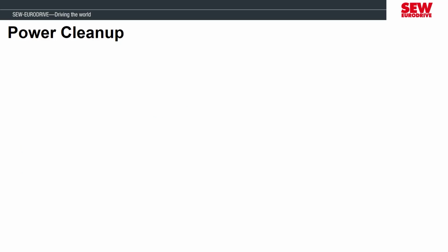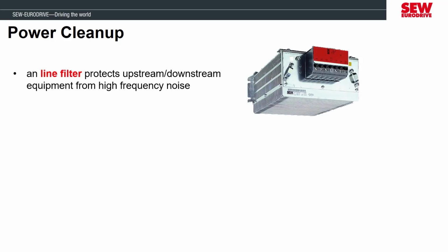Sometimes power is not always steady, or it could have a good bit of noise on the line because of all the machinery that's in a manufacturing plant. An inverter can generate a lot of electrical interference because it has to convert AC to DC and back to AC with rectifiers and transistors. This noise sometimes can radiate enough that it can cause issues with sensitive devices like PLCs and encoders.